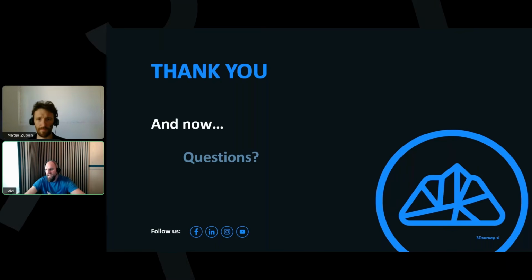There are now so many SLAM scanners coming on the market. We can maybe do a small teaser. We can already mention that we are preparing to release the next version, and in this one, 3D Survey automatically imports panoramas from the E57 data format. So typically this is what is done. But if you have, for example, just a regular 360 camera and you have the positions and orientation of those panoramas, in a future version it will probably be possible to import them with a specialized importer. We're adding these options because there are so many different ways these panoramas are stored, so you will get an option to import them differently.